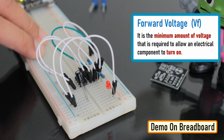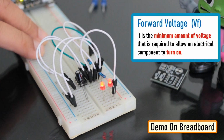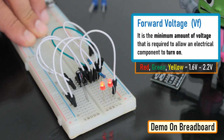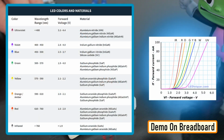Forward voltage is the minimum amount of voltage that is required to allow an electrical component to turn on. The red, green and yellow LEDs have relatively low forward voltage ranging from 1.6 to 2.2 volts and hence stay on longer when the capacitor slowly charges or discharges. However, blue and white LEDs start conducting from 2.5 to 4 volts and hence when the discharging capacitor voltage hits the threshold, the LED turns off faster than the other colors. I have provided a link on how the forward voltage works in the description below.